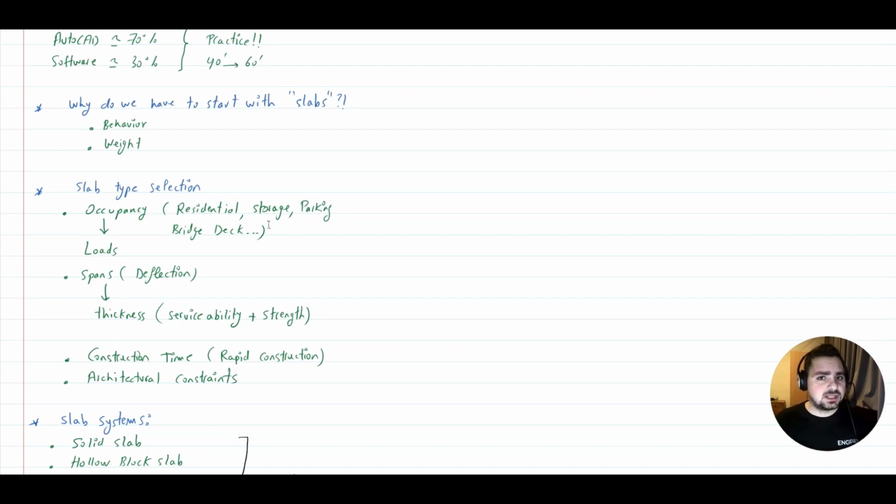Whereas for a post-tension slab system, first of all, it requires less labor, and second, you can remove 50% of the formwork right after 7 days only, and this will save you so much time. However, this does not mean that we do not use conventional reinforced concrete systems.